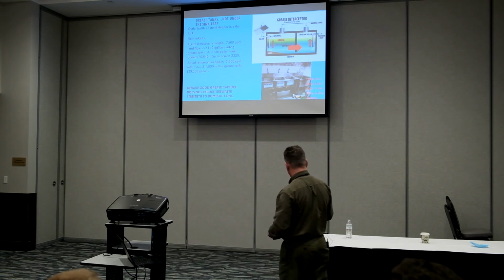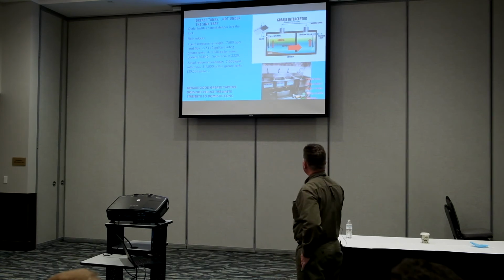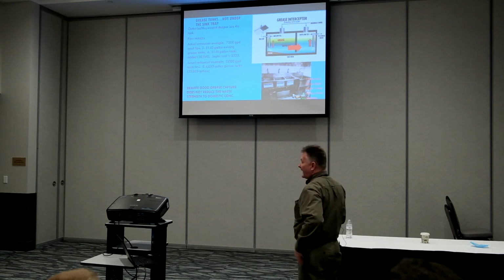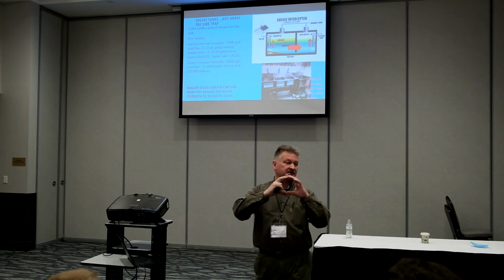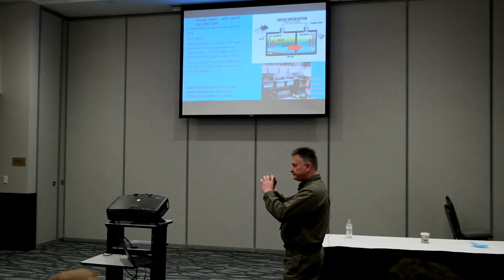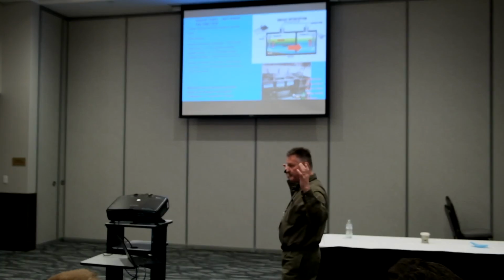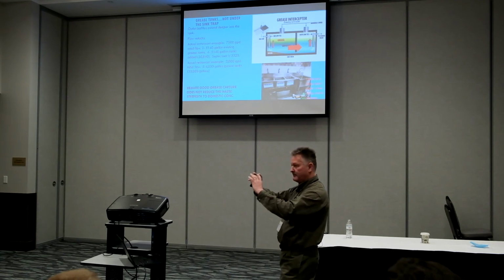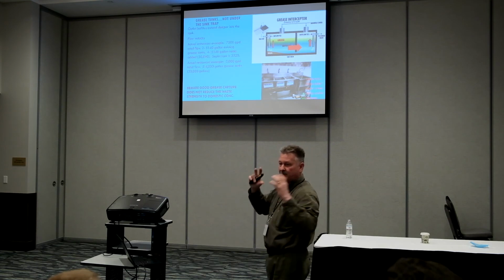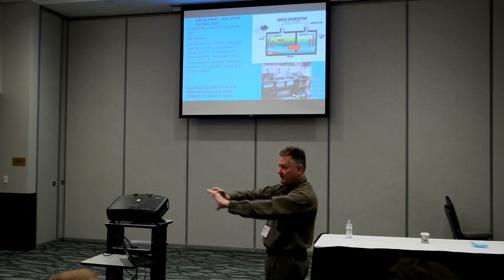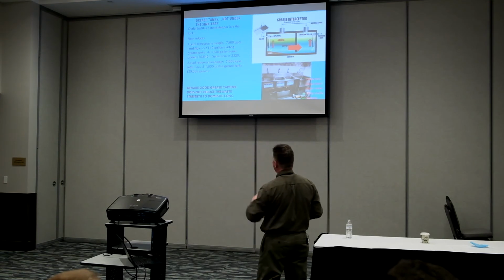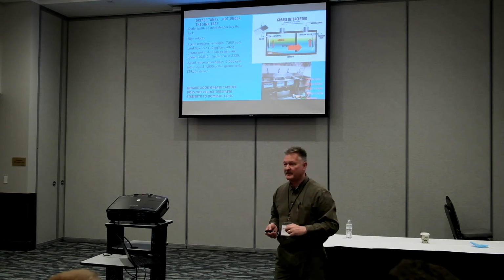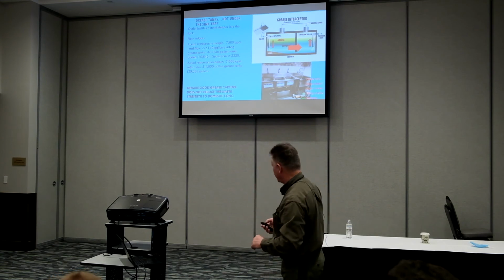But what we have to be concerned with is, say we get a lot of grease and oil right in here, and say our baffle wall just has a little 4-inch flow-through port like a standard septic tank. What happens to that? Physics: you've got a big volume right here, a little pass-through port, and then you open up again. What happens? We get an increase in velocity. So we can have a tendency to pull things through that system. So maybe a double compartment tank may not be as beneficial as we think, but we have to consider that in design.